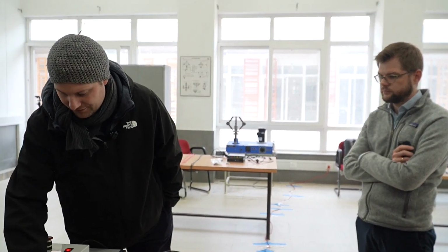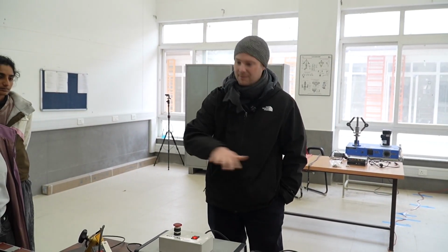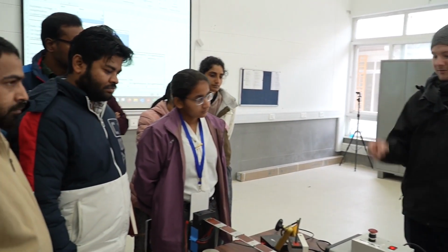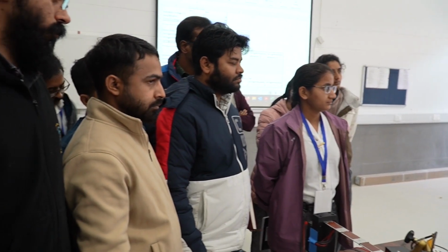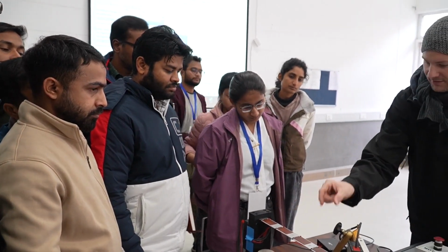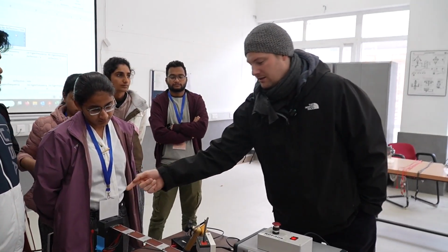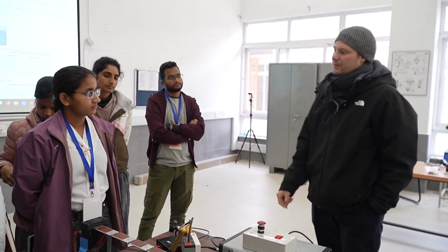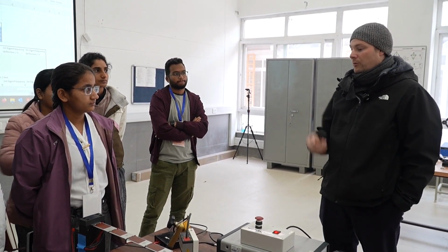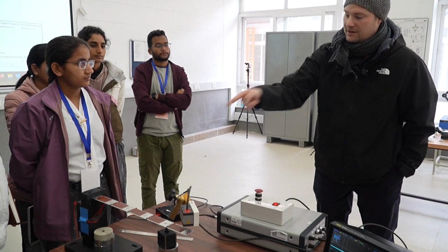What is also written in the task sheet, we will look whether we can detect the eigenfrequencies of at least the first and the second mode shape. The third probably will be too high in this setup to get it done due to various factors. But the first two we want to have, and if we have them, then we try to get at least one mode shape by switching the laser from point to point, measuring these distances, and then measuring the deflection along the axis for each mode shape by looking at the maximum deflection while we have the sine on the first piezo patch.